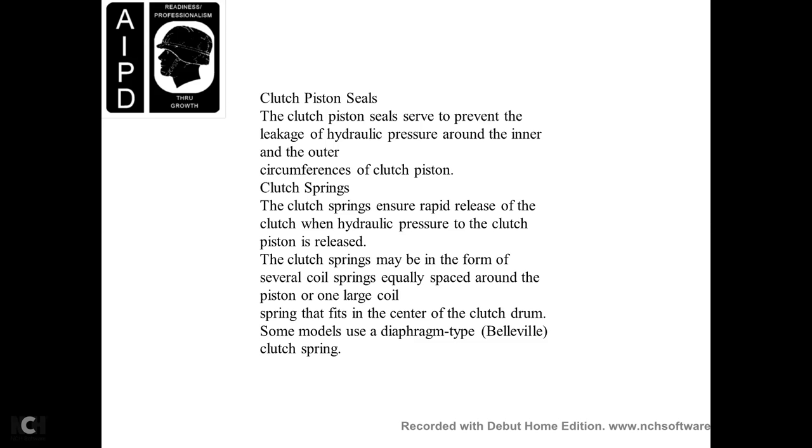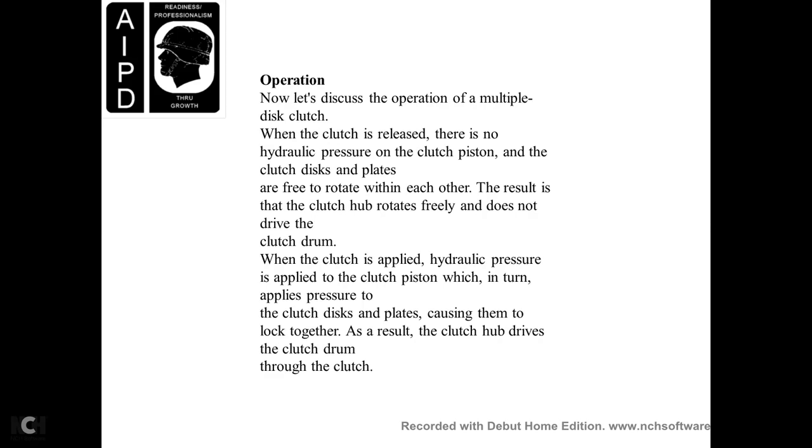The clutch springs may be in the form of several coil springs equally spaced around the piston, or a large coil spring in the forward center of the clutch drum. Some models use a diaphragm-type Belleville clutch spring. Operation. Now let's discover the operation of the multiple disc clutch.